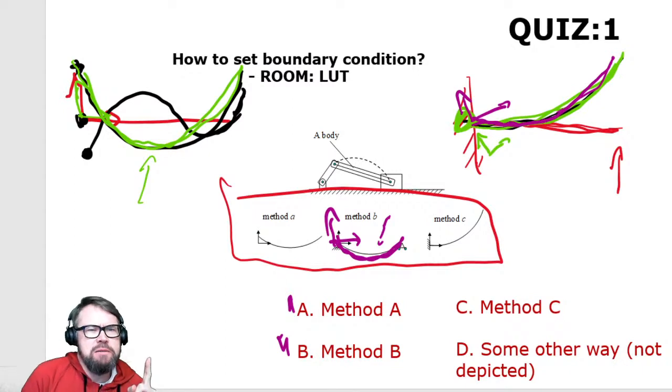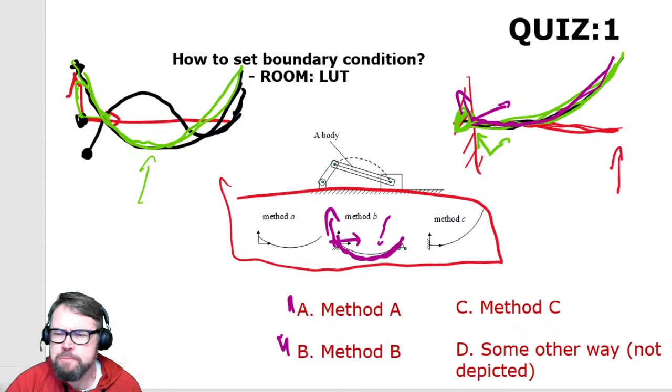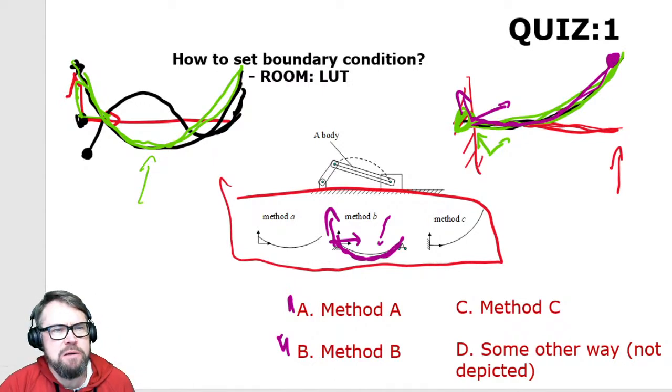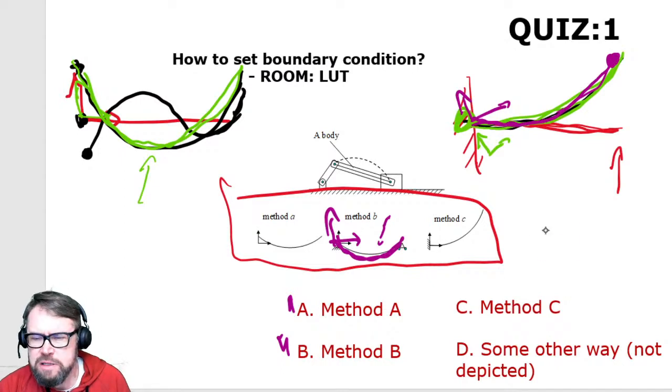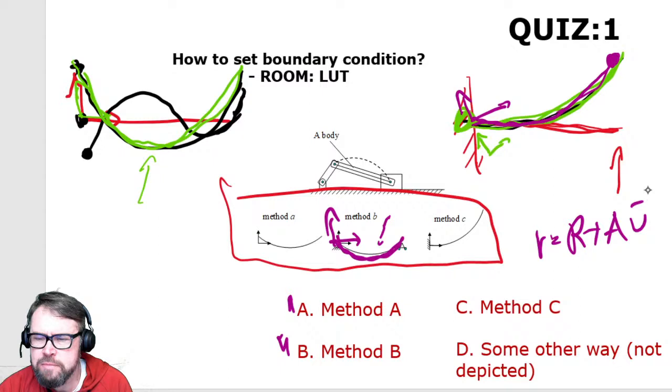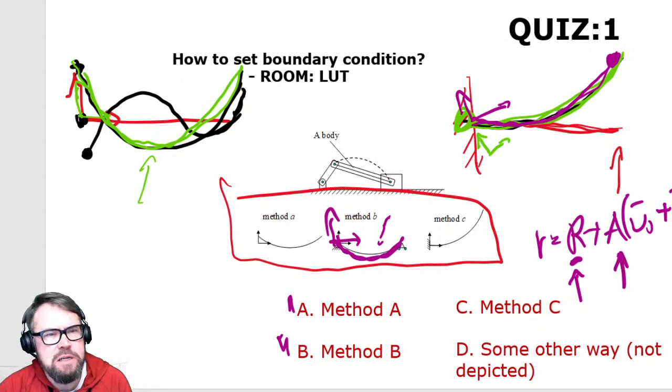Because remember, what we're doing in multibody dynamics is describing a particle, let's say the particle that is now located at the free end of the cantilever beam, by using this equation. To be thorough, what really matters is whether we have the same final destination. It doesn't really matter if you do this trip by moving this guy or this guy or this guy. What matters is whether we have the same final destination. And we do, regardless of what reference condition we're using here.